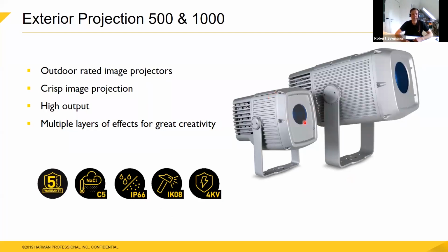And typically, most fixtures, you can say the weakest point will be the front glass, obviously. And so basically, when you do the test, you take a metal ball and you more or less throw it at a certain distance, and then there are different weights, and IK goes from IK1 to IK10. So this is a fairly high standard that really gives you some trust that this product will not break if somebody, let's say, throws a stone at it.